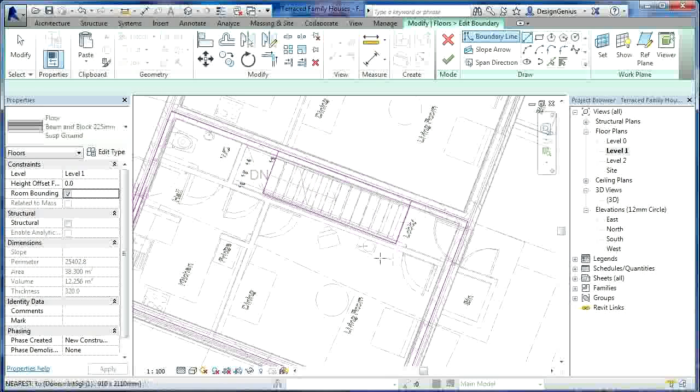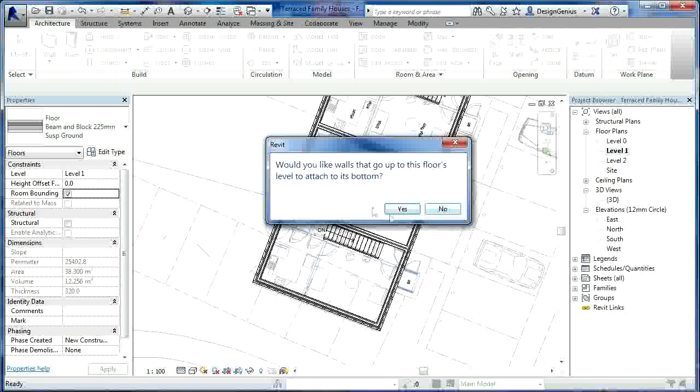They must all form a closed loop, so I need to break this line. So if I break that line there, and then what I can then do is to fillet that and that. I'll fillet that and that. You need to click on the sides you want to keep. Always remember that, the sides you want to keep. Now that that is done, I'll just click OK.